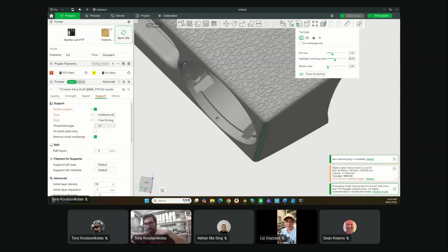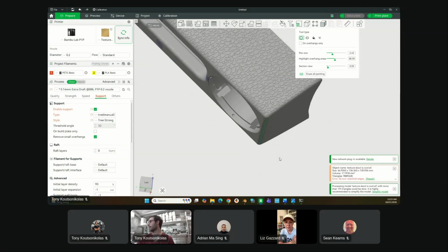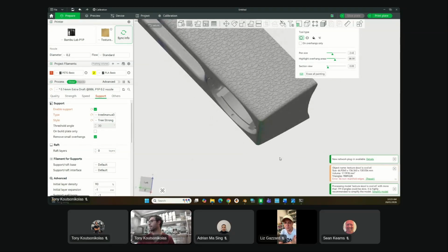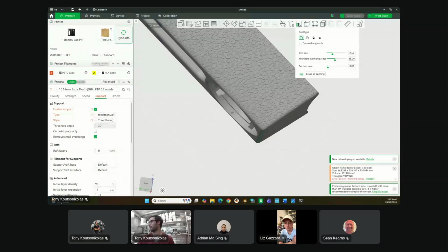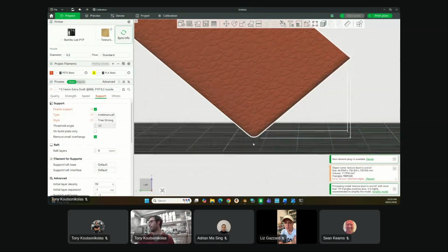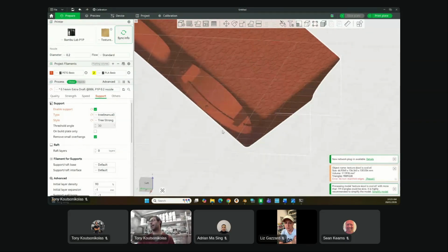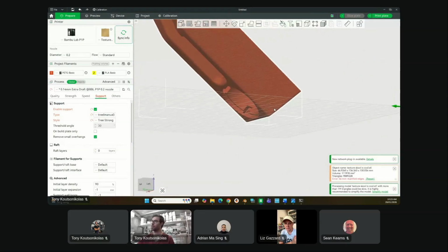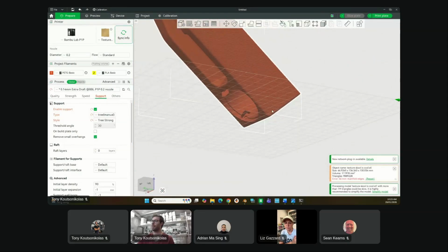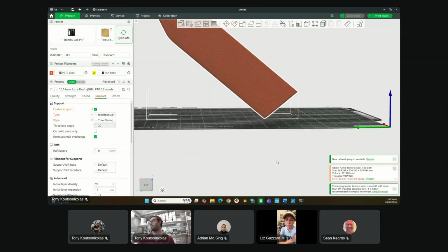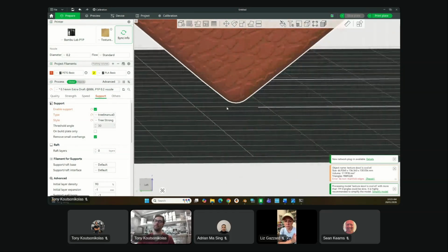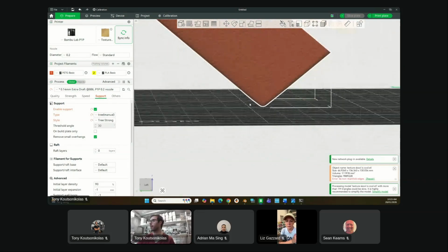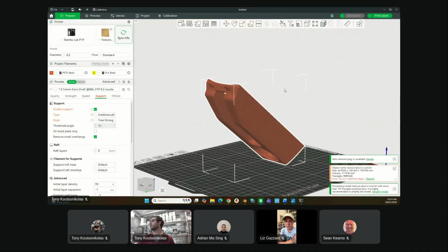Like, imagine if you can make the entire design specifically for them. The other overhang that I see, or the other kind of hard part of this, is that the very first layer is on a fillet, a rounded edge. That could be a chamfer as well, potentially. It kind of depends. That's the top part of this console, so maybe that's why that bit's a fillet. I know definitely the inside of the cup holder doesn't need to be a big fillet like that. Maybe you could cut the tiniest flat edge here, but you're going to use a brim anyway, so it's probably fine. Cool beans.